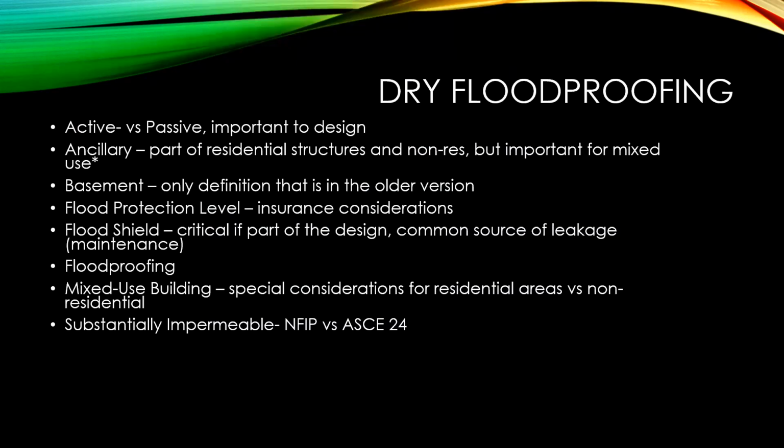Okay, so with that said, I think we've got a pretty good handle on wet floodproofing. And so in contrast to that, I want to talk about dry floodproofing. We don't actually encounter this a whole lot in Kansas, but I think it's worth being a bit familiar with if you haven't really worked with it before, just to know what to expect, because it is very complicated and there's a lot that goes into one of these designs, and then I'll show you the certificate for it. So active versus passive types of floodproofing measures. Active requires human intervention, passive do not.